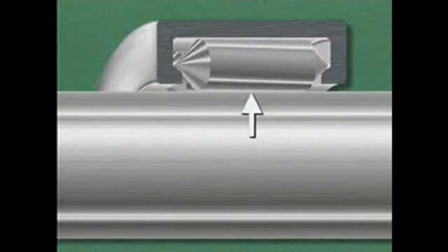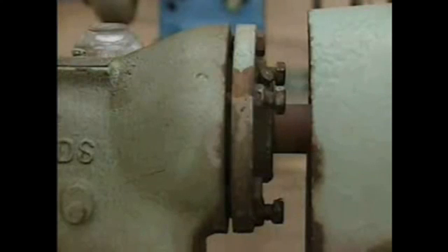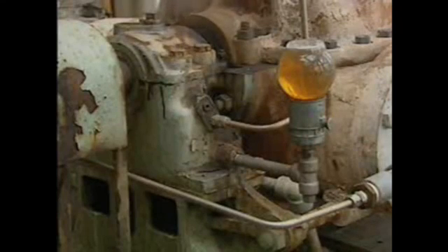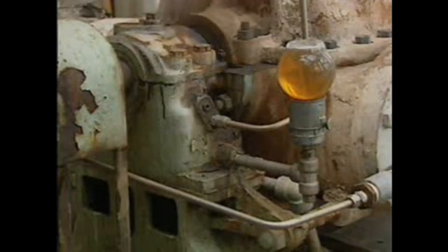This kind of mounting is often used when there is not much space around the shaft. Bearings are usually enclosed in housings. The housing is the part that surrounds a bearing and holds it in place. In order to support the bearing, the housing must be able to handle the types of load that the bearing is subjected to. The load is usually transferred from the shaft to the bearing to the housing. Most housings contain lubricant for the bearing, and they also prevent dirt and other contaminants from getting into the bearing.